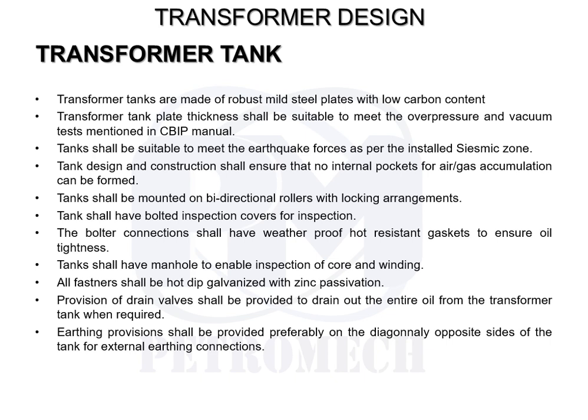Another important point: we have to be very sure in which seismic location the transformer, whether indoor or outdoor, is placed. It's seismic zone 2, 3, 4, whatever. Accordingly we have to design the tank so that it can withstand the earthquake force as per the seismic zone. Tank design and construction has to ensure that no internal pockets for air or gas can accumulate. The transformer tank at the bottom will have bidirectional rollers with locking arrangements for movement.